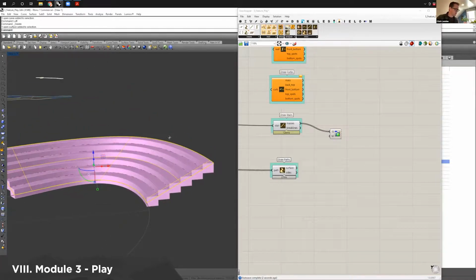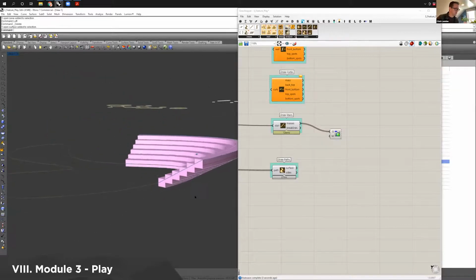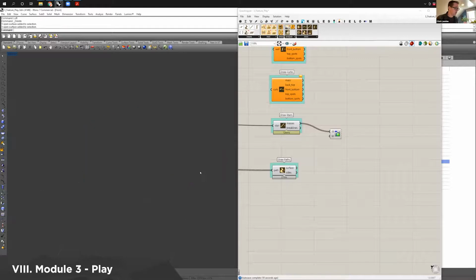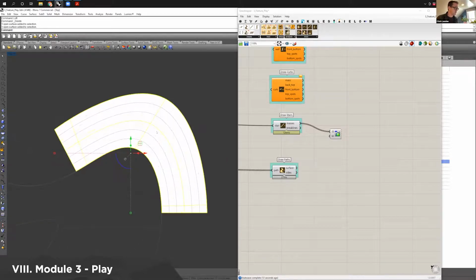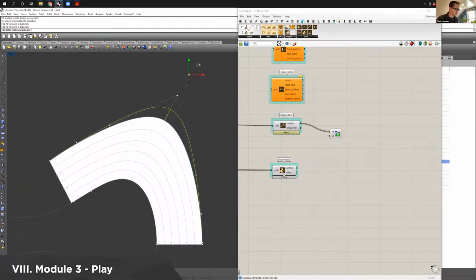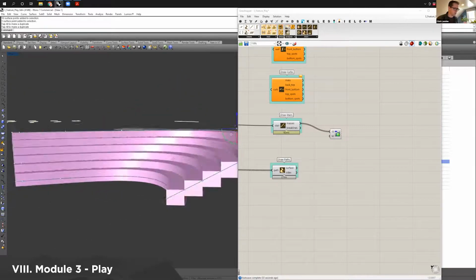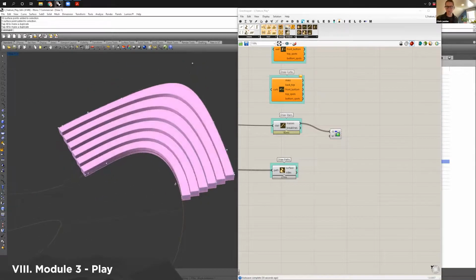And I've got my bubblegum stairs here. So that is a great way to manipulate and create an amphitheater that has 1.5 foot steps. And the neat thing here is, because it's a surface, I can also do F10 and turn on my surface points, and I could just drag this out here, change that surface, and I'm manipulating the surface to describe the stairs in a different way.